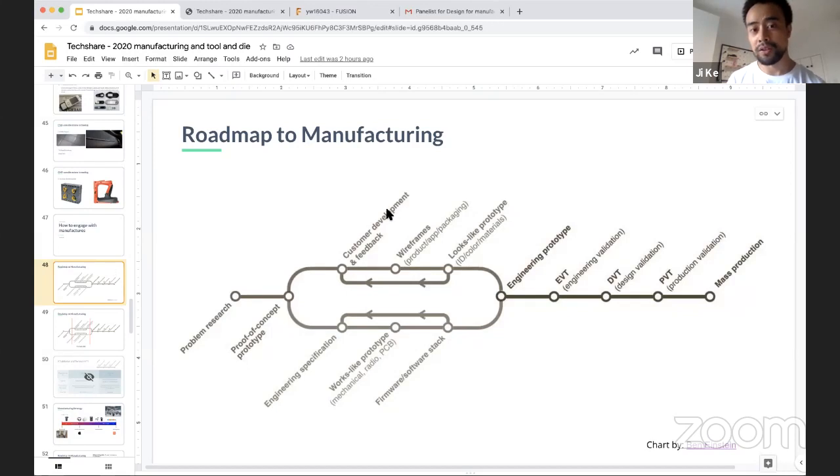How long does it take? So certifications depend, right? If you're looking at CE, it's only accepted in Europe, right? America has the UL and FCC. And Canada has something different, China has something different, India has something different, right? So the good thing is that if you apply for equivalent CE and FCC, the certification process can be done in one go. So let's say you approach SGS, saying, hey, I want CE and FCC for this device, and they'll do the tests at the same time. And then how long does it take to obtain those? It really depends on what kind of certification you're looking for.